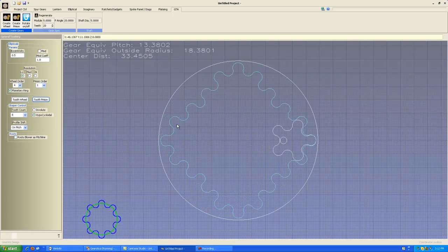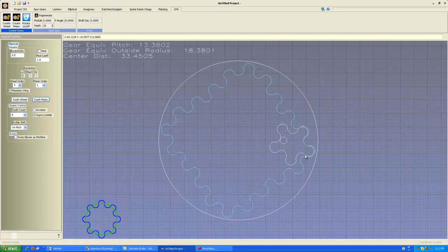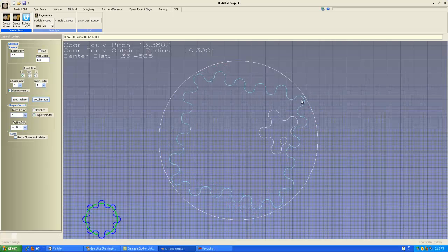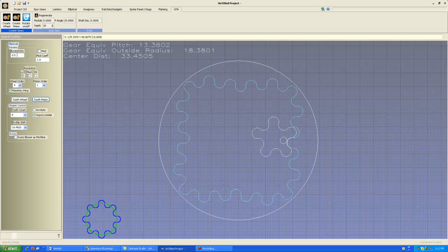And you'll see that depending on the eccentricity that you've got on an elliptical planetary, your teeth may or may not fit in the corners. And as you can see on the meshing, this one is actually cutting off a bit. This would work fine if you just filed off a little bit on a tooth on a corner. For those that want decorative gears, little modifications like that probably aren't asking too much. But if you don't want it to hit those points, lower your eccentricity.